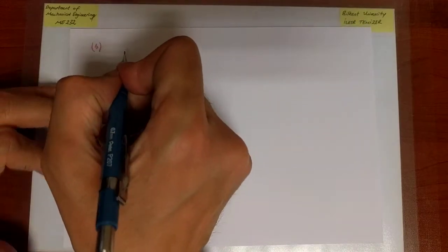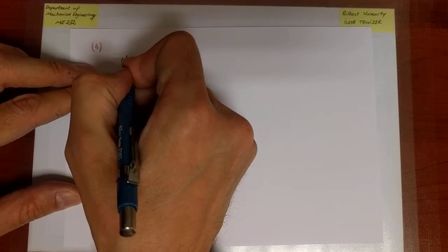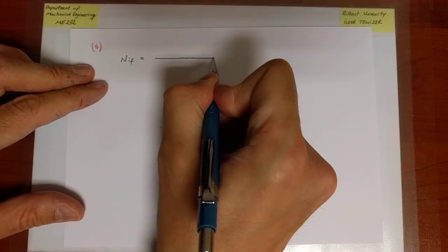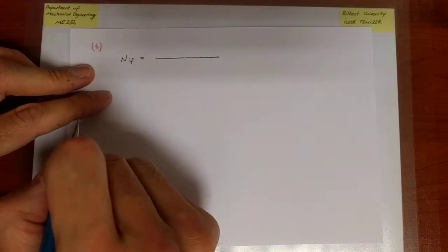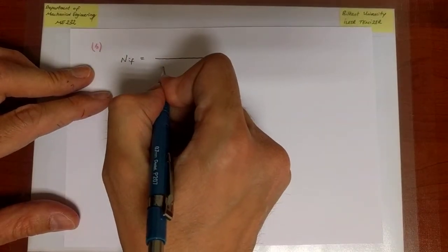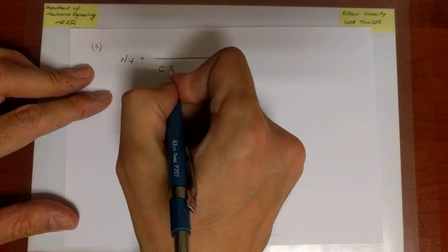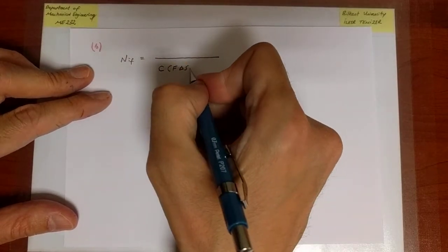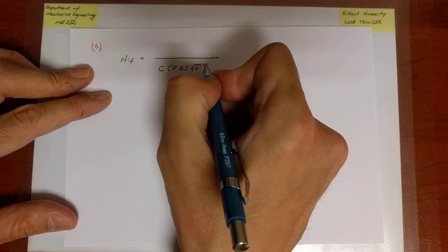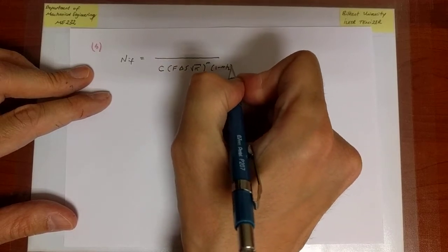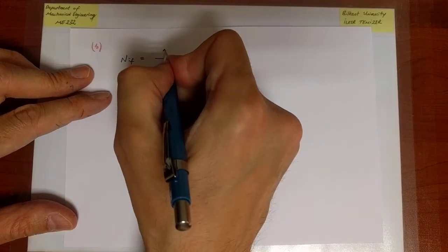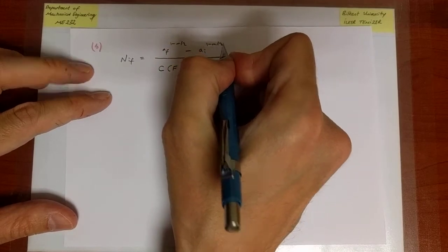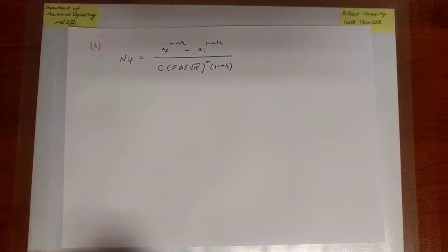And our equation said that if the parameters that appear in the ideal form of the Paris equation are indeed constants, a constant C, F if it's a constant, and it's not, I know, neither is C in general, then I can write the life estimate as follows, for M not equal to 2. That's our life estimate.